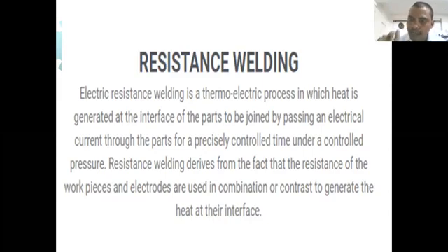And this high ampere heats the joint because the heat generated in resistance welding can be expressed by the equation H equal to I square RT. So my dear student, this is about resistance welding. I hope you can understand how resistance welding works.